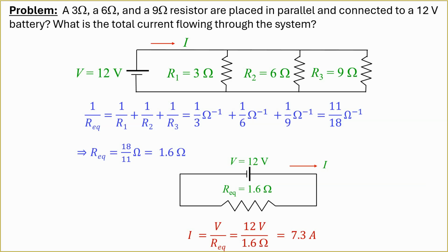So if you want your circuit to produce the biggest amount of current, then you would always add your loads, your bulbs or your lamps or your hair dryers, whatever you want to connect, in parallel if you want a large current passing through them.